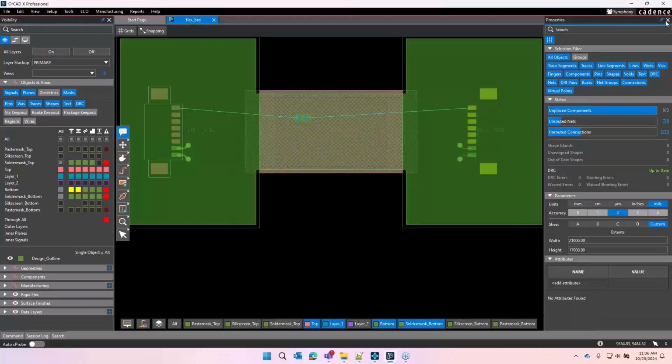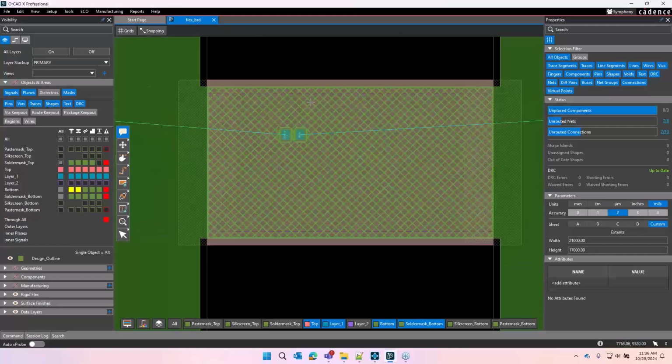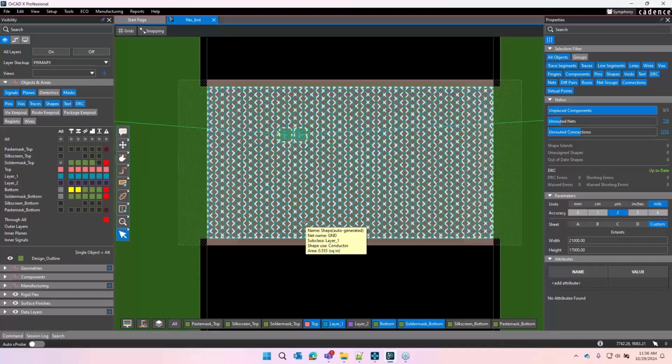Okay, so that's the design review. That's a look at the stack up, a look at the ground planes. And we can also take a look at this crosshatch section right here. So Lauren had mentioned that for flexibility of the bending area, we want to have that crosshatched. And you can specify what that's actually going to be crosshatched like.